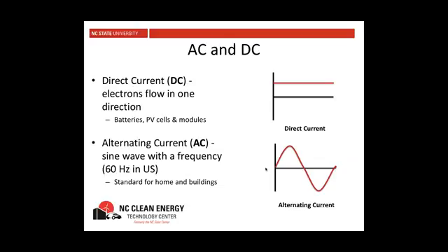If you could slow this down, 60 hertz is very rapid movement of this current in a sine wave. If you could slow it down, you might actually see a flicker. Like if you're looking at a light bulb and it's being supplied by alternating current, there's this very brief moment in time where the voltage actually goes to 0. There's 0 pressure as we switch from the positive to the negative. So you might actually see a slight flicker. You probably wouldn't see it, but you could. If you could slow this down enough, you might see a slight flicker in your bulb because there's actually 0 pressure at every intersection of this sine wave with this black line, which is the 0 volts.